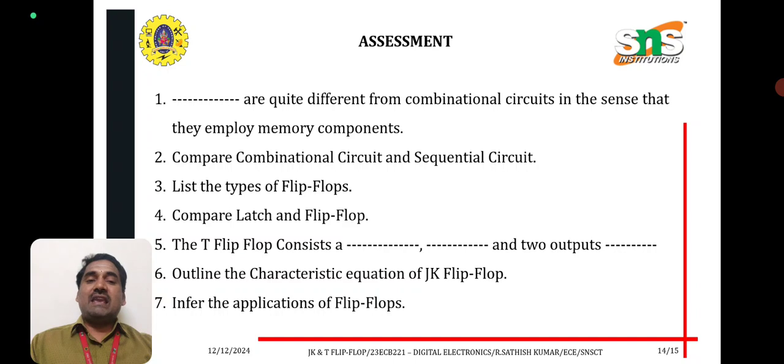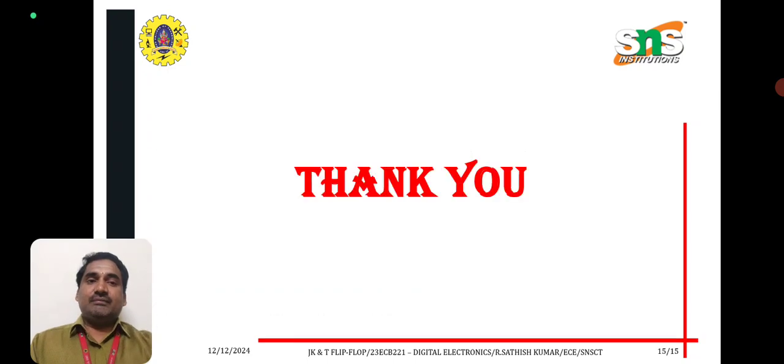Outline the characteristic equation of JK flip-flop. Qn plus 1 is equal to J into Qn bar plus K bar into Qn. The applications of flip-flops: it is used in memory units, registers, shift registers, storage registers, counters, frequency dividers, etc. Thank you.